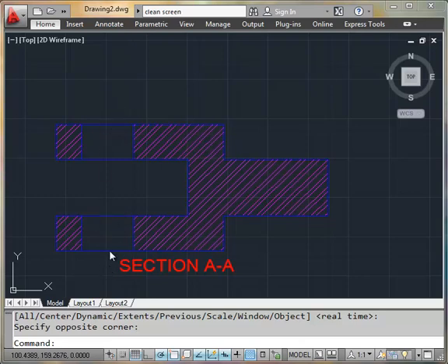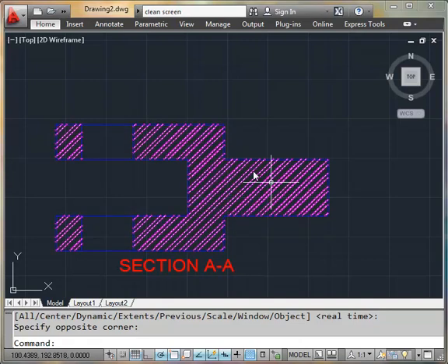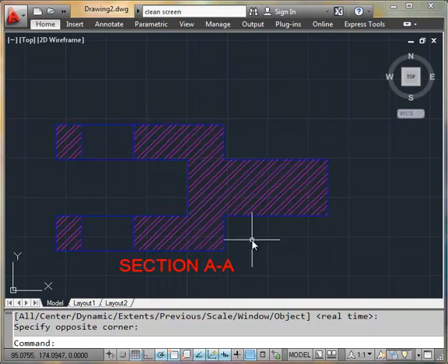Now I've still got these lines in because since I'm looking at it, this would be the very top of the arc. Just picture it going like this. And then this is the end part here that is once again solid. So that's a quick look at how a section view works. And then the hatch is a single object using the hatch command, and this particular pattern indicates that this part is made out of steel.